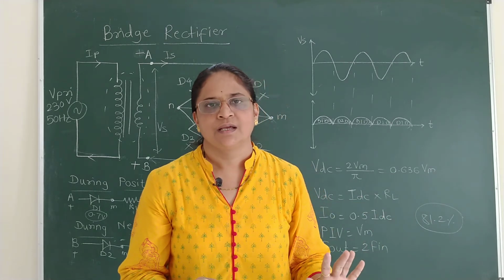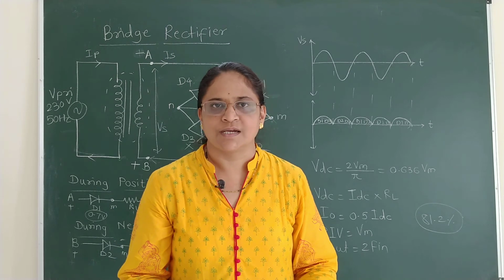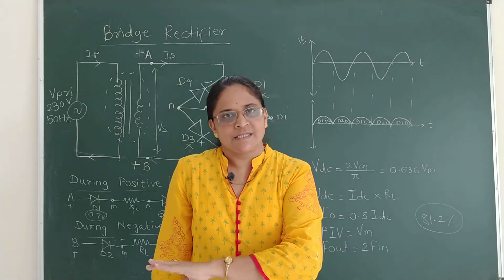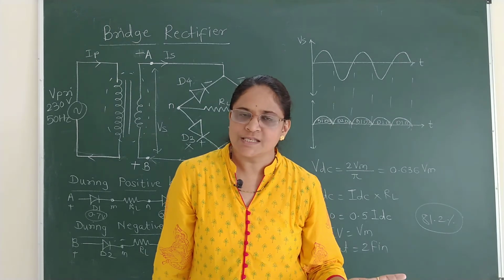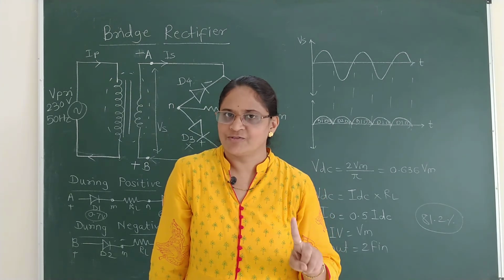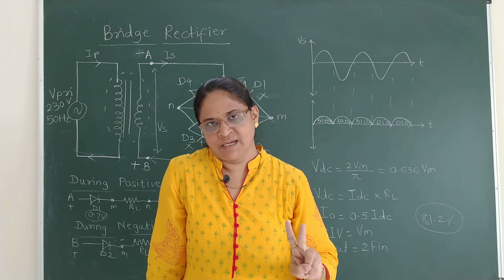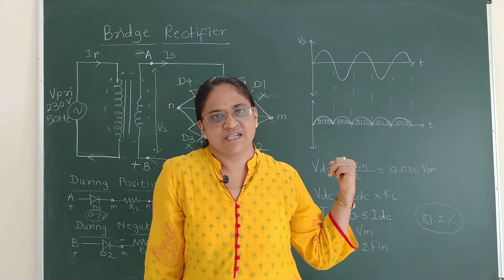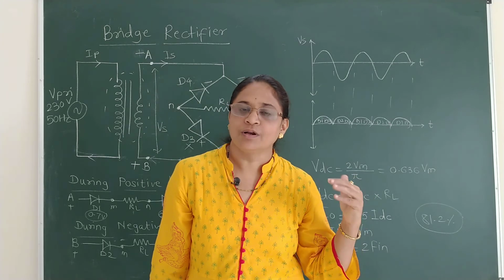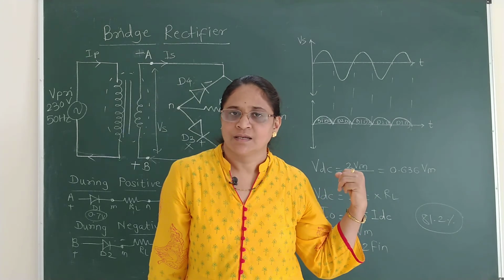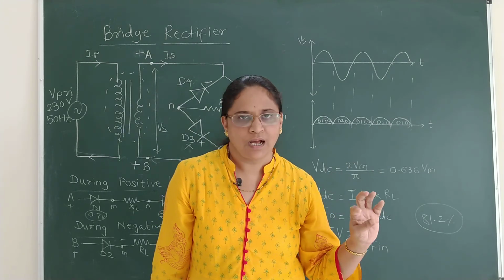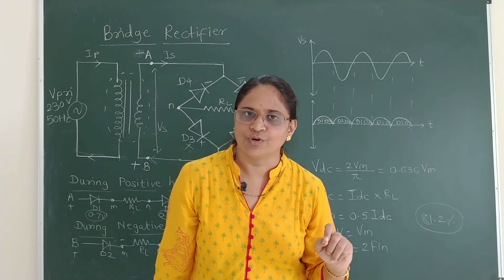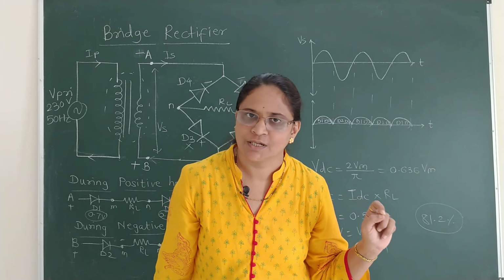So in this way, for every electronic circuit, whenever there is a need for a DC power supply, AC is to be converted into DC by using either a half-wave rectifier, full-wave rectifier or bridge rectifier. But a bridge rectifier is not suitable for low DC voltage, as two diodes conduct for either half cycle and they need minimum 1.4 volt to overcome the internal depletion layer.